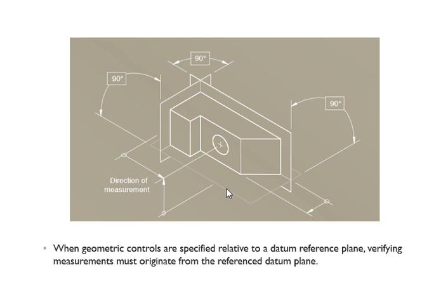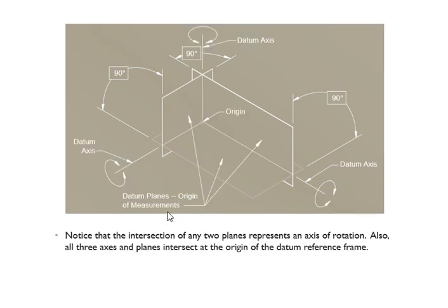Of course, datum plane, like I said, you measure stuff from there. So when you do the verification of the measurement, you're checking if your measurement is accurate. All the measurements are verified or drawn from your plane, the datum plane. Therefore, if you want to verify from here to here, you are going to measure from this plane. That's what it's talking about. If you want something else, then you also choose the plane that is in contact with that measurement. Okay, then we take the part out of it.